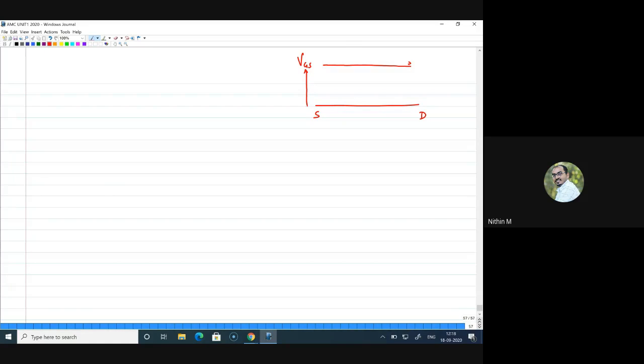I'm just pictorially representing. Now VGS has to be more than VT. Say for example, this is the VT. When I apply VGS, it has to be equal to or slightly more than VT. Then only I will actually get a channel, right?